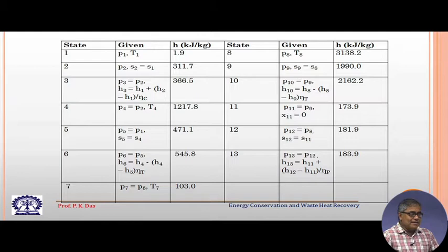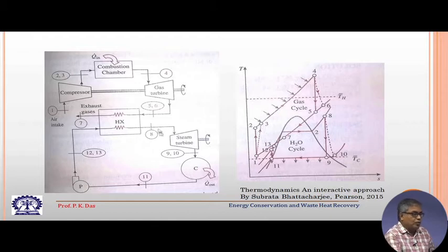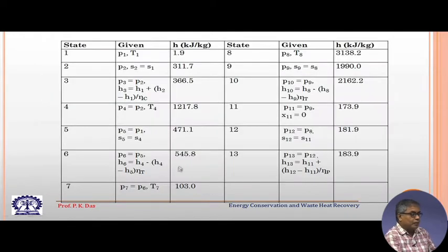So, it enters that heat exchanger and exchanges heat with the bottoming cycle, so that steam can be generated. I am talking about this heat exchanger. After point 6 the gas stream goes into that heat exchanger and is cooled to point 7. So, at least up to point 7 we have to do the calculation to know the property, particularly enthalpy, and let us go back.